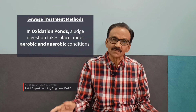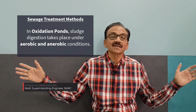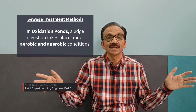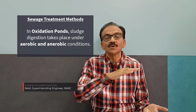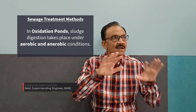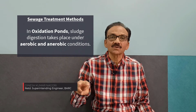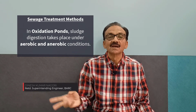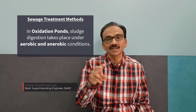So now coming back to our treatment plant, another system is the oxidation pond. See, an oxidation pond is also like a septic tank. Oxidation ponds are constructed for big housing colonies or big industrial areas. These tanks are, say, 30 meters by 30 meters, and the depth will be around 1 to 1.5 meters. It is constructed in the open, and the only difference is that the septic tank works on the principle of anaerobic action, whereas in an oxidation pond both aerobic as well as anaerobic systems are working.